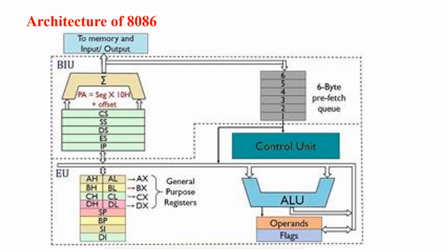The 8086 microprocessor is a 16-bit processor with two main parts: the bus interface unit, and the second one is the execution unit. Let us see one by one. The bus interface unit handles the communication with the memory and input-output devices. It fetches instructions from memory, calculates addresses, and handles the data transfer. Instruction queue: it stores up to 6 instructions in advance to speed up processing.